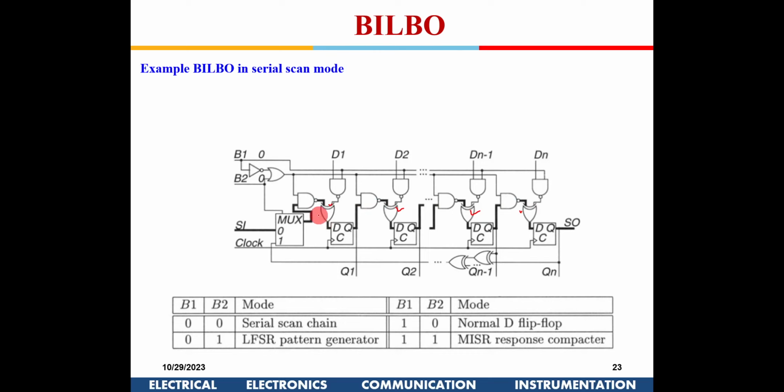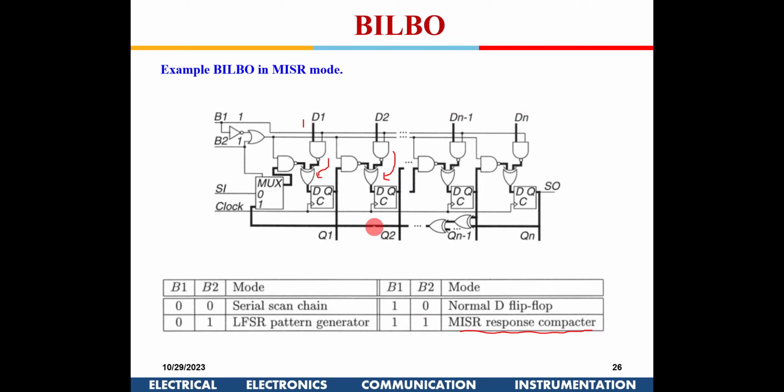So it is shown in the MISR board. So these XOR gates will come, and continuously the data will come here, and it will generate the signature. So you can just give this 1 1, and you keep running the test waveform. So this is one universal register. You could have these universal registers, and depending on the control signals, you could program this for one of the 4 operations.